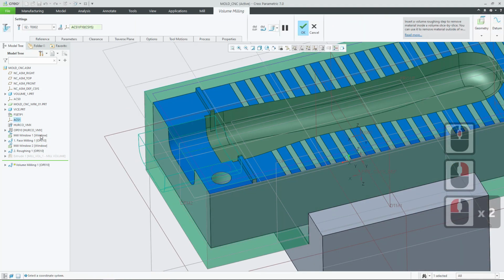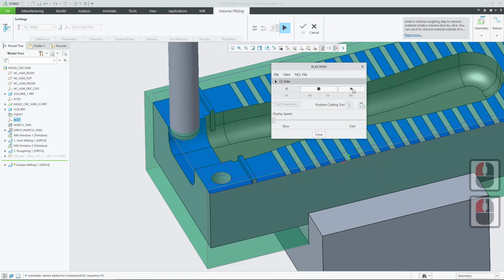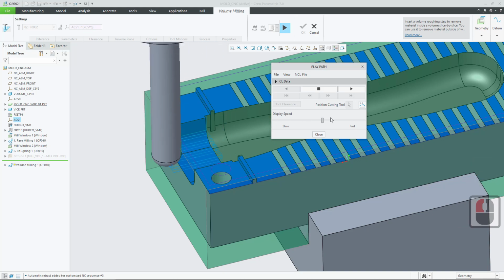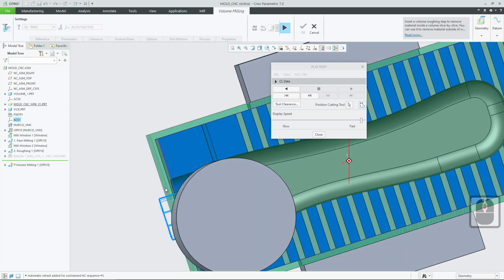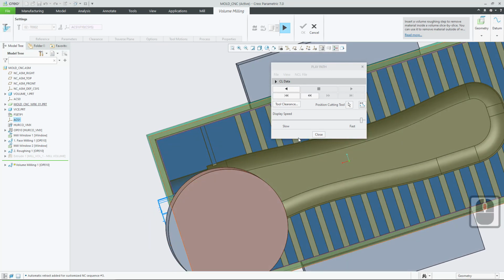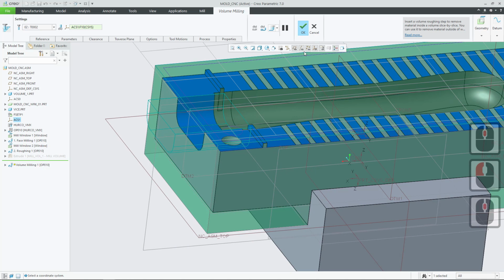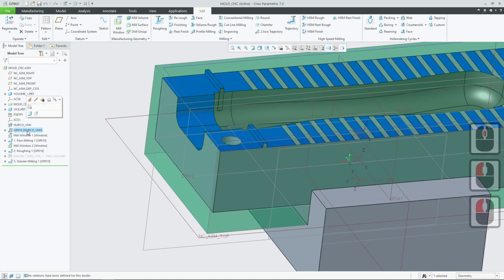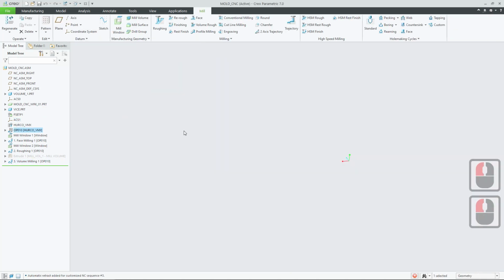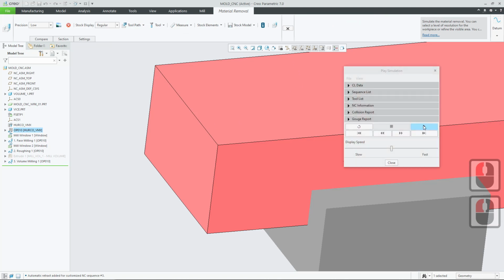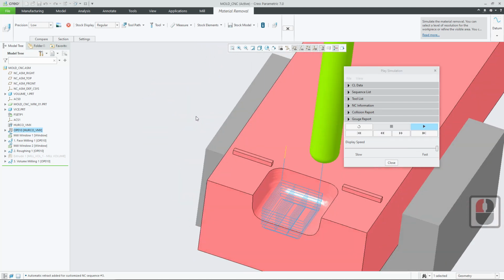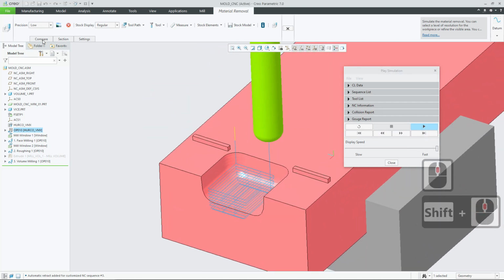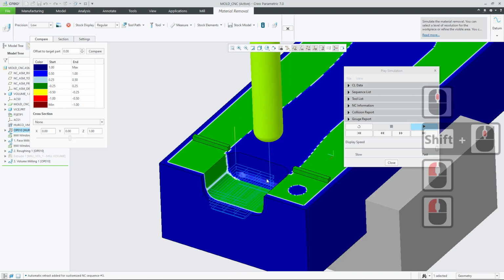So I'm just trying to get a preview of the toolpath. So there's the toolpath. So it's going well outside of our workpiece now. So it should break through. And if we wanted to simulate that, we could come back out and say simulate stock removal, play, maybe speed this right up. Yeah, that's arguably better for our purposes in this particular part.